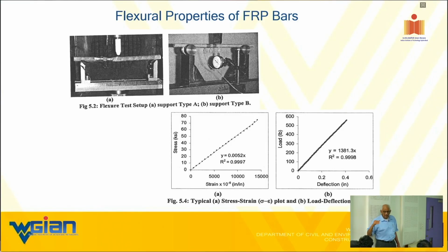The high strength concretes are 5, 6. So that is bad news because steel is incompatible from the strain point of view. If both are acting in unison in terms of strain, it would behave better than otherwise. What happens is the steel gets debonded quicker than FRP. The affinity is always the issue.